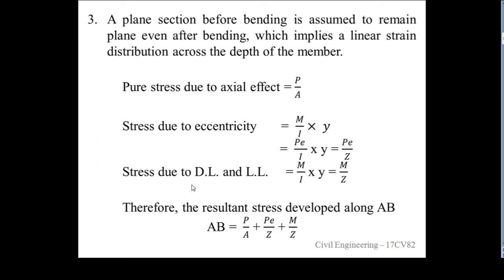Then the stress due to dead load and live load is M by I into y, where M is the moment due to dead load and live load. That is equal to M by Z, where Z is the section modulus.